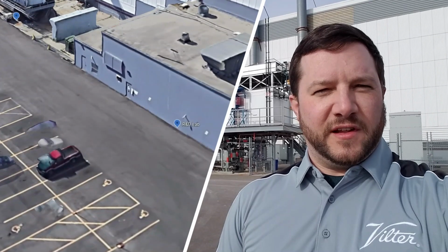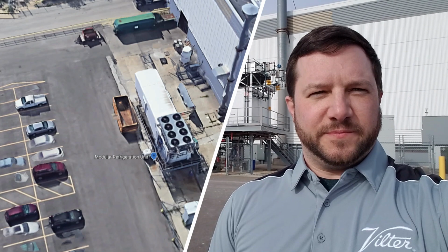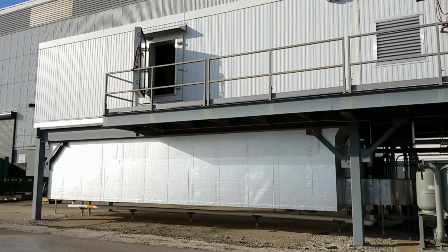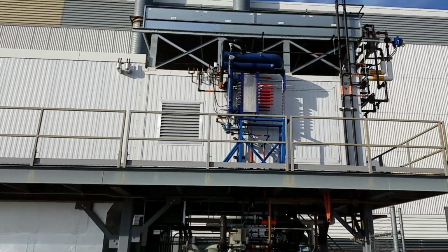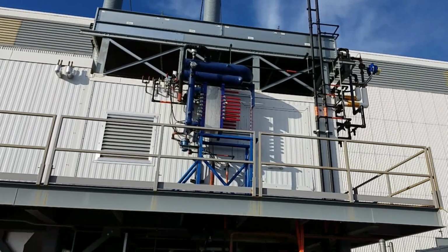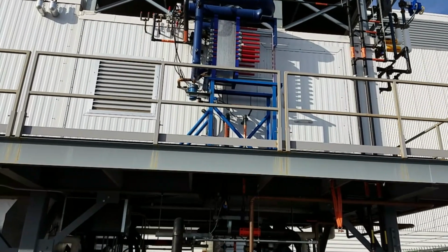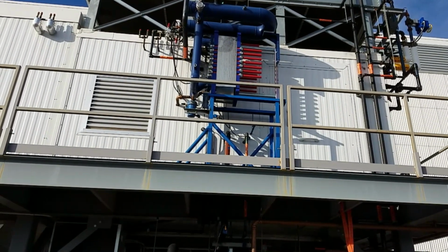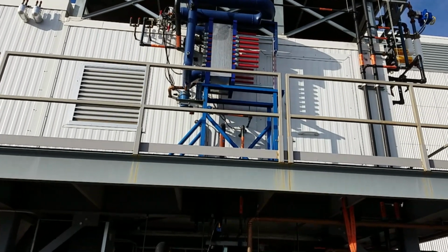My name is Steve Seelar, and I will be introducing our Modular Refrigeration Unit. Our MRU consists of three major components: our evap room, engine room, and air-cooled condenser. We have our cascade heat exchanger outside. This is condensing CO2 from a gas to a liquid, using flooded ammonia to transfer the heat between the two.